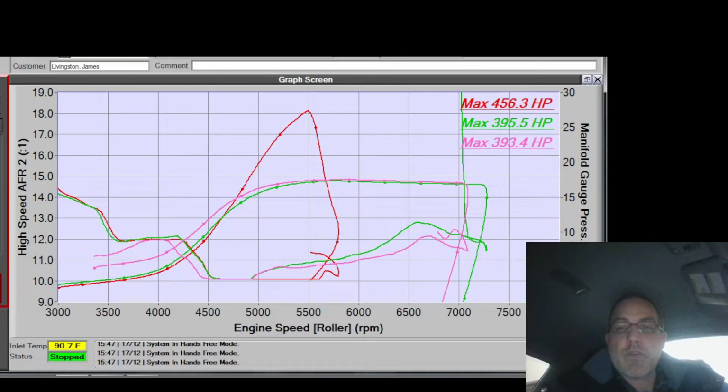47, my VE is what? Oh, interesting. The ethanol had a little wiggle in there. 47 is still almost the same boost pressure, and the VE is 106. So it thinks the 106 is too much.